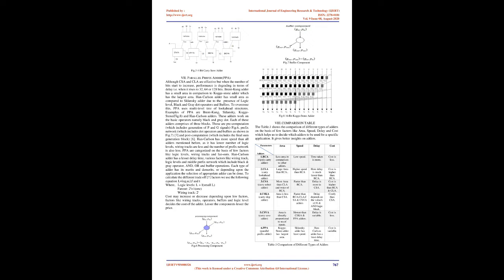This type of adder uses both RCA and CLA for calculation. It is faster than RCA, CLA, CSA and CSLA adders. Depending upon the Pi signal output from the N logic block, the carry is selected. If the output of the N logic block is 1, then CIN, skipping the addition via FAs, is selected as carry, and if 0 is the output, then carry is generated via FAs. The delay depends on the values of Pi and the N logic block. If the N logic block gives output as 1, then calculation over FAs is skipped, or else calculation happens via FAs.